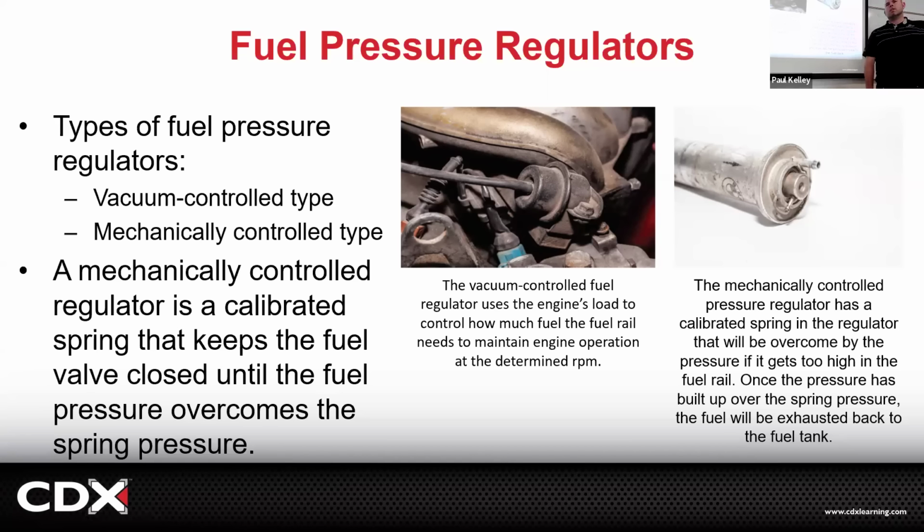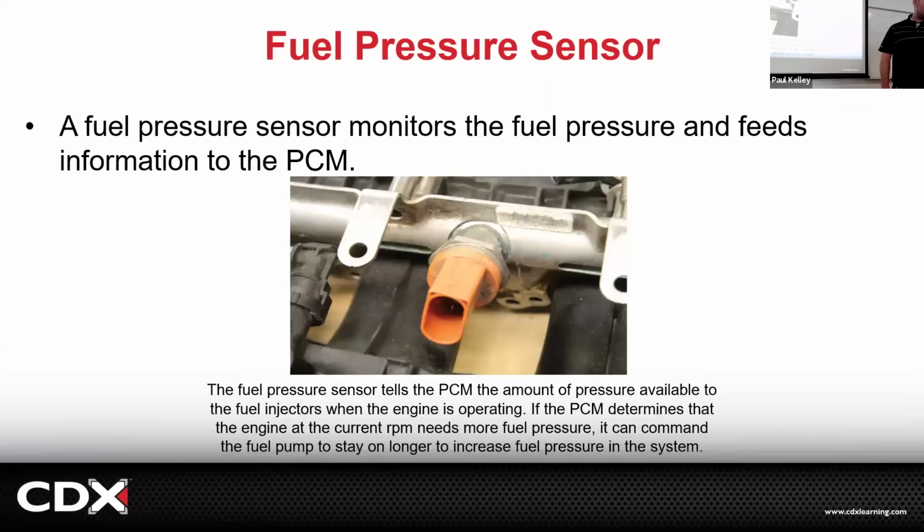Sadly, no. If it's direct injection, absolutely. If it's port fuel injected, probably not. Like let's say we look at this fuel pressure sensor. Do you see how it's right in the rail? That costs a little bit of money to do. And this is a pressure transducer. So that's going to measure pressure and make it into an electrical signal and send it to the ECM. So there's a cost there.